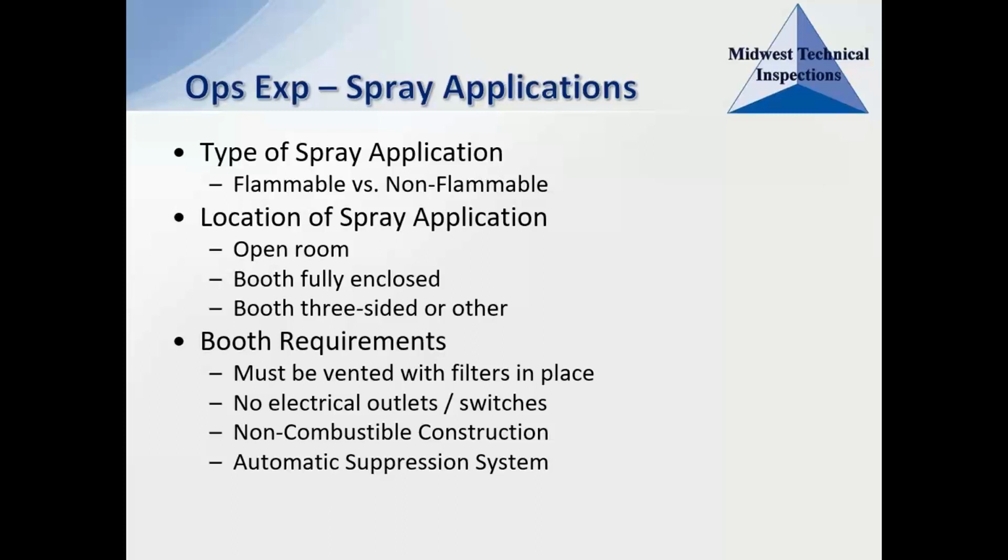Now there is a requirement. The NFPA says that there should be an automatic suppression system inside of that spray booth. So it's a chemical spray that can spray down onto the booth if there were to be a fire inside there. This is one of those areas that a lot of our clients are kind of indifferent to. They don't necessarily care if there's the suppression system or not. They kind of say, that's kind of overkill. That's not required. But the NFPA code does say it should have the suppression system.